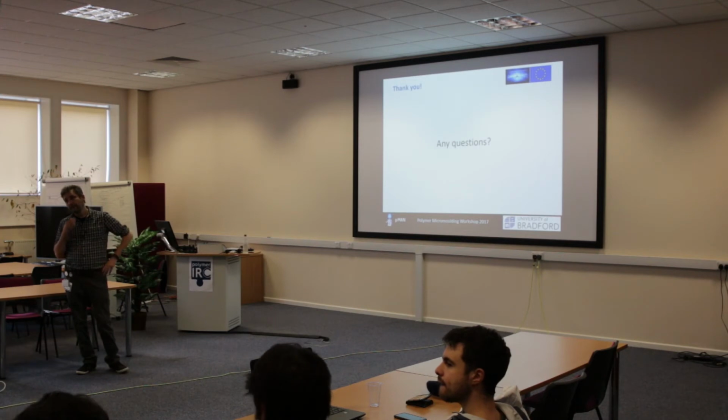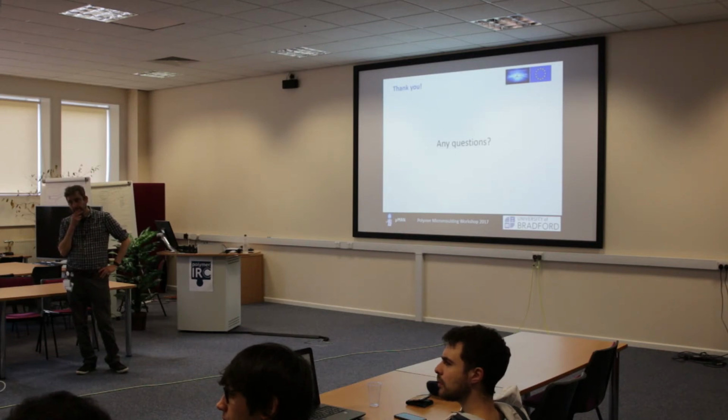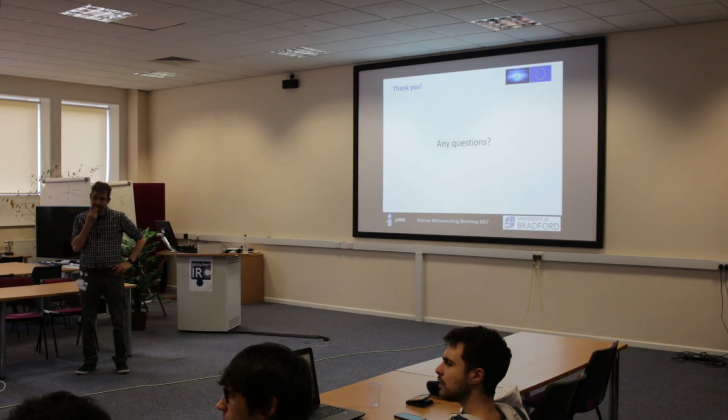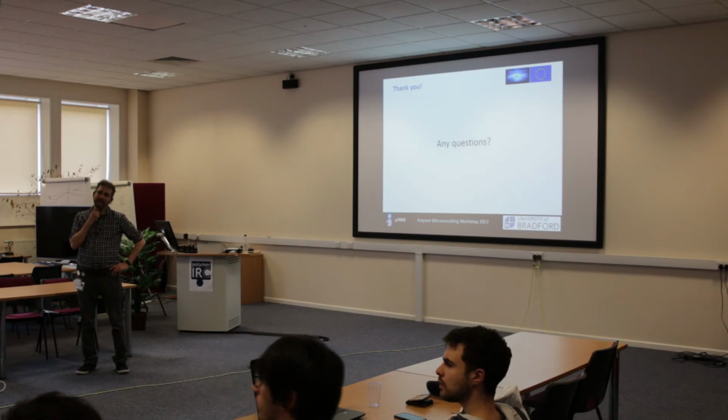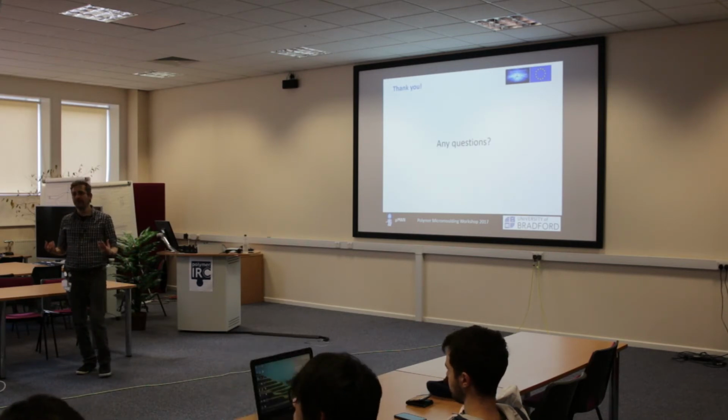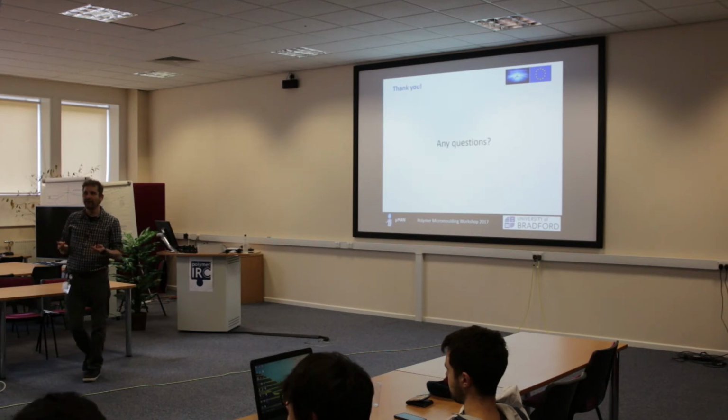So when you're blow molding that bottle, there is a die, and inside it's air. Yes. So when you are cooling it, it absorbs some water from the air inside it. Yeah, but it takes time for water to get into polymer. It's not an instantaneous thing.